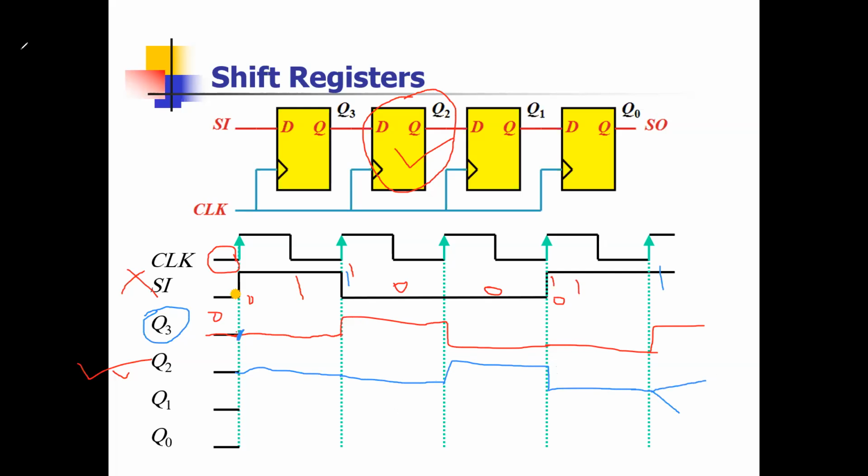Okay, 0. Girls, now you can see, look. Here, before in the data, 1 was here. Now check for the 1 shift. 1 was here, now after that, is 1 shifting to the right side or not? Check. Yes. Shift register. Can you see the shifting is occurring? Yes. So this is called a right shift register.